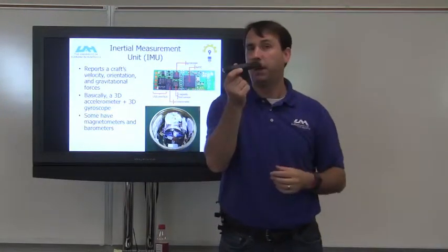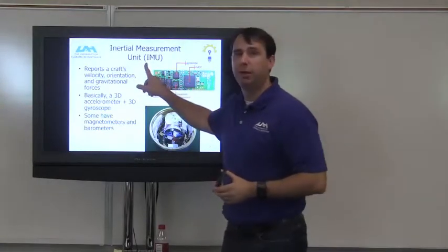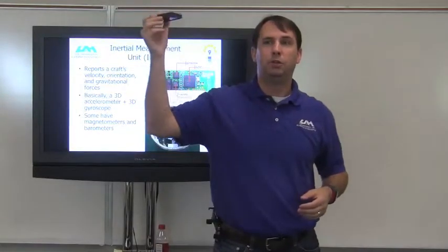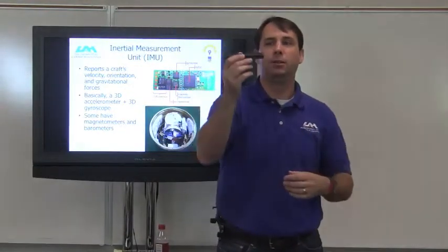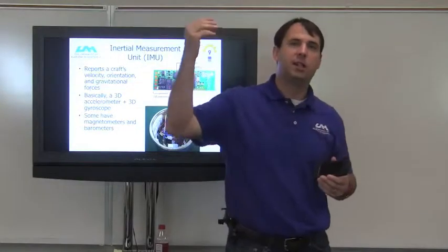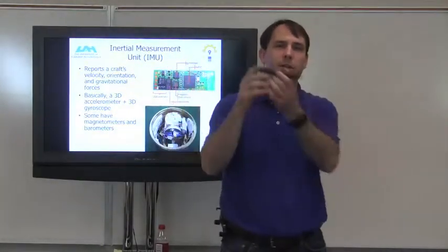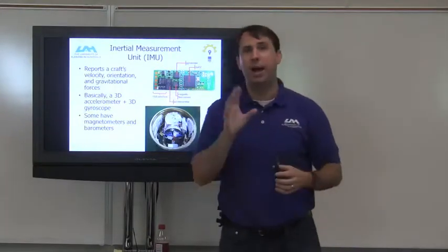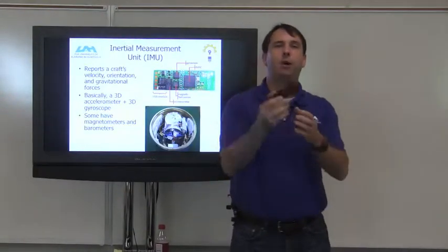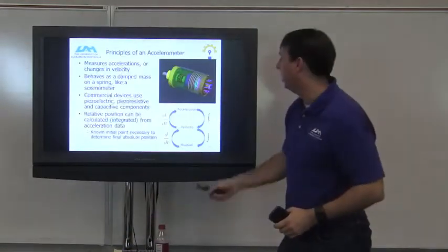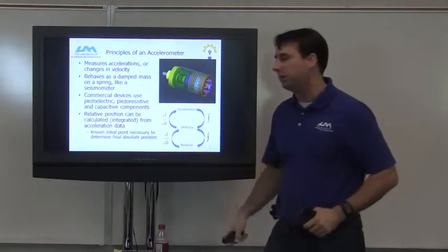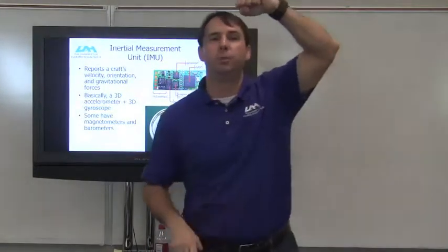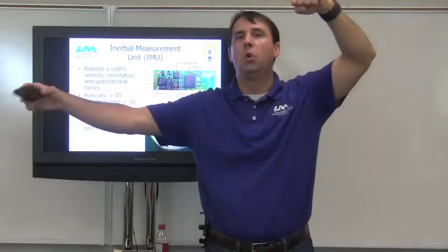But what your payload can do is start measuring with the IMU, and the IMU can tell it, okay, you've traveled, you've felt these accelerations. So it knows the accelerations you're feeling and how long you felt them. It knows if you're spinning because it knows its orientation. So the IMU can tell you how far, based on the acceleration, velocity, and position relationship. From a known start point, the IMU can tell you where you ended up.